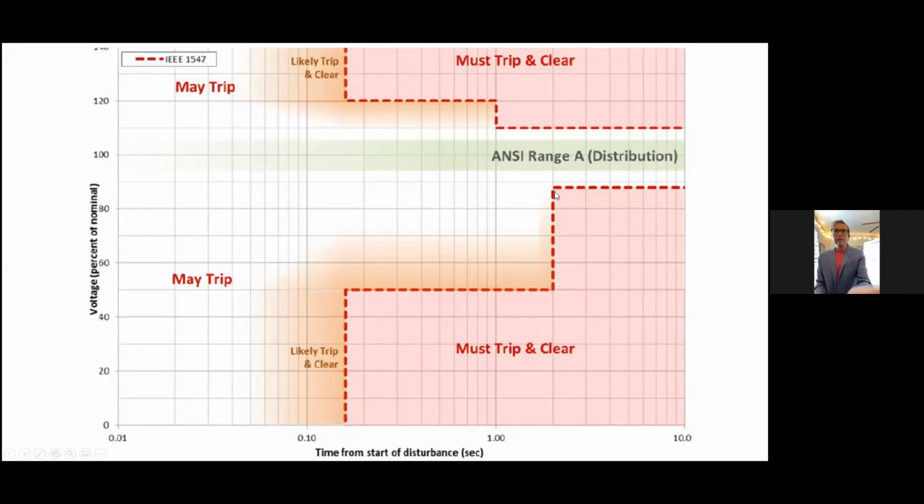So basically, if grid voltage has dropped down to 80% of normal and 2 seconds has passed, you absolutely must trip. And if grid voltage gets really wacky, like 40% of normal, I need you to trip off after like 0.2 of a second. So basically this green range says stay on, and these darker pink or red ranges say you absolutely must trip offline. Again, this was back to the safety standards put into place with the IEEE 1547-2003 revision. This is basically what that looked like.